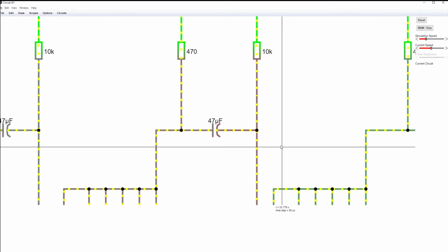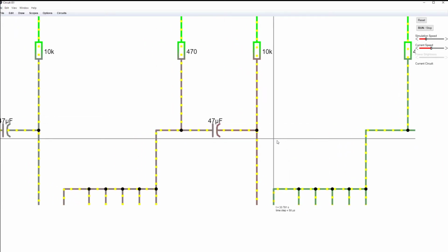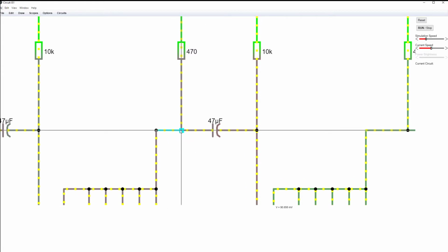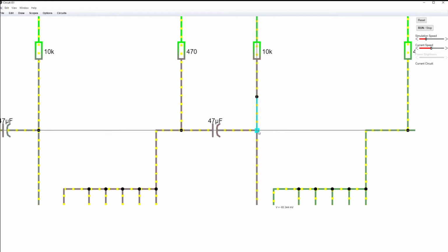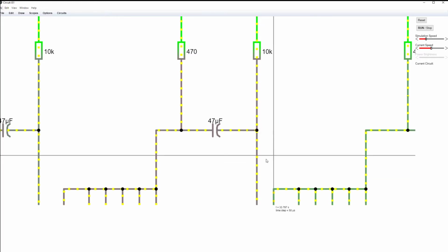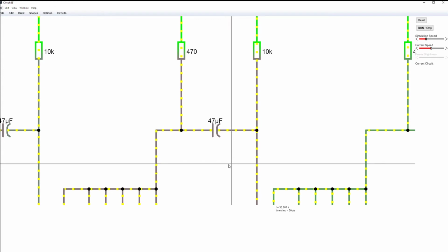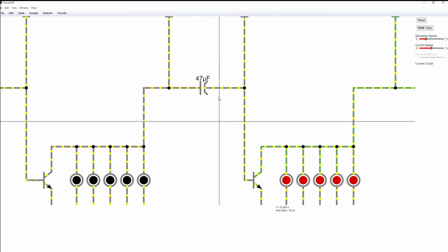We can see over here this capacitor actually has a bit of a red tinge to it. If I hover my mouse over this end of the capacitor, we can see in our bottom right hand corner that our voltage is 90 millivolts. But if we look at the other side of the capacitor, we have a negative voltage. Right now it was negative 90, but it's going back up to 0, as you see the color going more to grey. So we are somehow in this circuit having a negative voltage. There's a lot of weird stuff happening here.